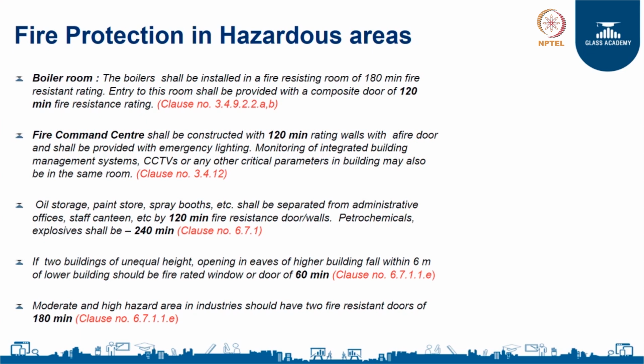Now, in such areas there is a high possibility that a fire that begins will be of high intensity, and it is very important that we look at a longer duration of fire protection, which is clearly stated in the NBC as well. So, if you look at a boiler room, it clearly states a 180-minute fire resistance rating, or if you look at a command center, nothing less than a 2-hour fire resistance rating.